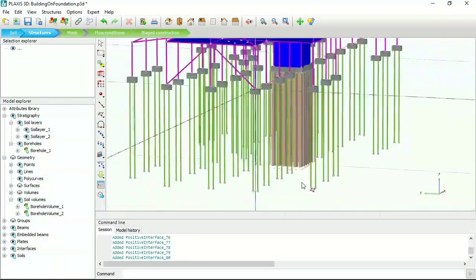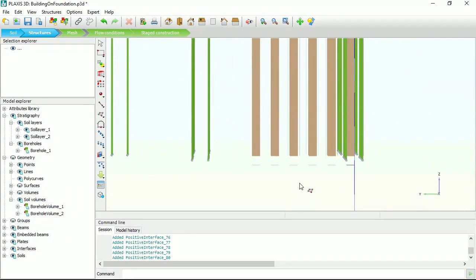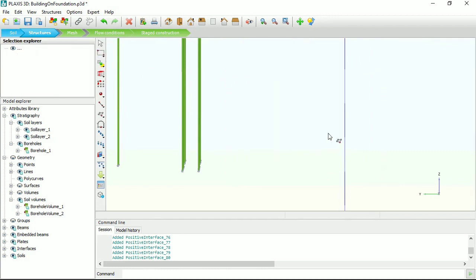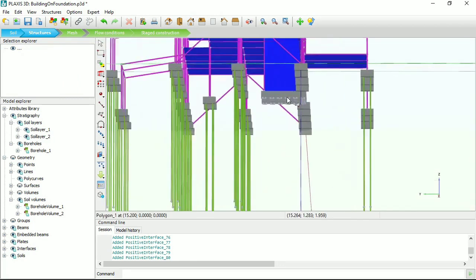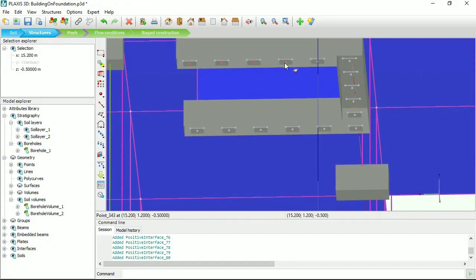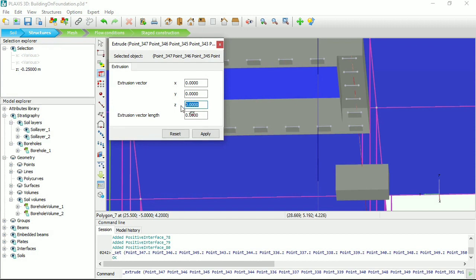There's been some question asked to me during my presentation how to generate and obtain from this volume pile structural forces, because those piles are being modeled as volumes. The calculation will only provide as results stresses. So one technique consists of introducing what we call dummy beams, which is what I'm going to demonstrate right now. So along the central line of this volume pile, I will create a beam, the purpose of which is to monitor the evolution of the change of curvature and elongation, axial deformation, without introducing significant additional stiffness.